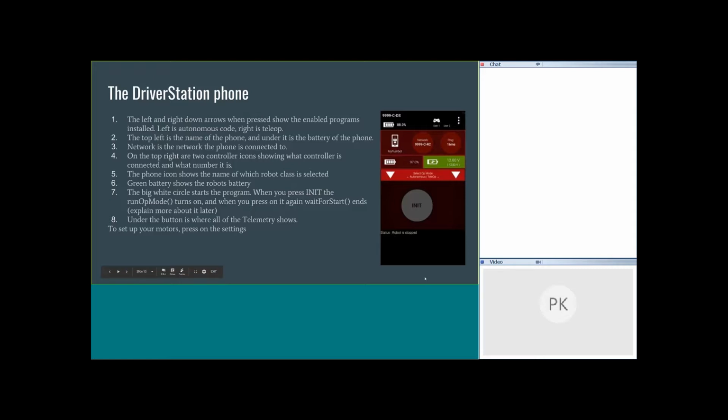Here you could see messages that the robot prints out. So it's very useful, for example, to print here everything you can print: the angle of the motors, the angle of the robot, the distance, all the sensors. Because when you have errors in your code, that we'll talk about in the next webinar, you're going to want to see what those errors are. And using the information that you have is the best way to find out what's wrong.